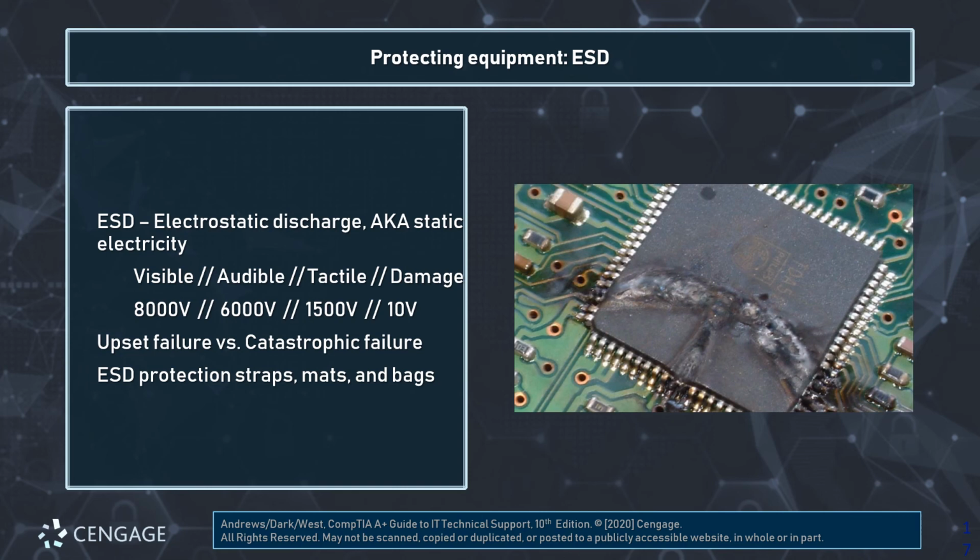Pretty major changeover. So make sure that you're not leaving ESD up to chance. When you're working with a particular object, always follow procedure and use your anti-static straps, mats, and bags, which we will provide in abundance while you're in the lab with us.